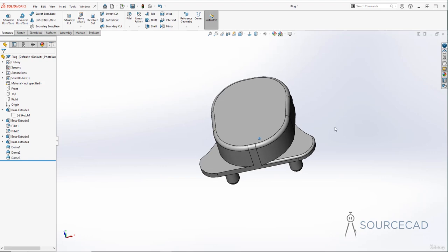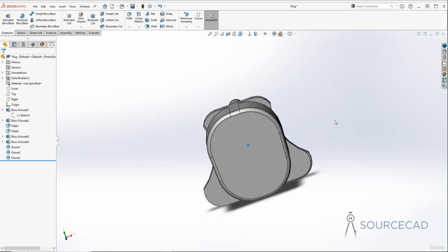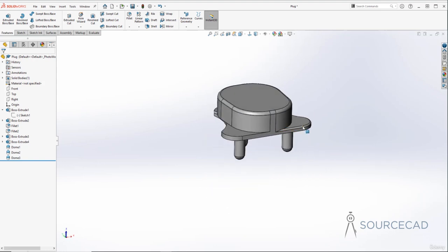For example, in this case, we do have a small problem. If you notice this, we have a fillet here, but we don't have that here. Initially we had a fillet on this side of the drawing as well, but now we don't. So you just need to make these smaller modifications if required, but in most cases, replace sketch entity will be able to fix your sketches without altering anything down the line. So that's the replace entity tool.